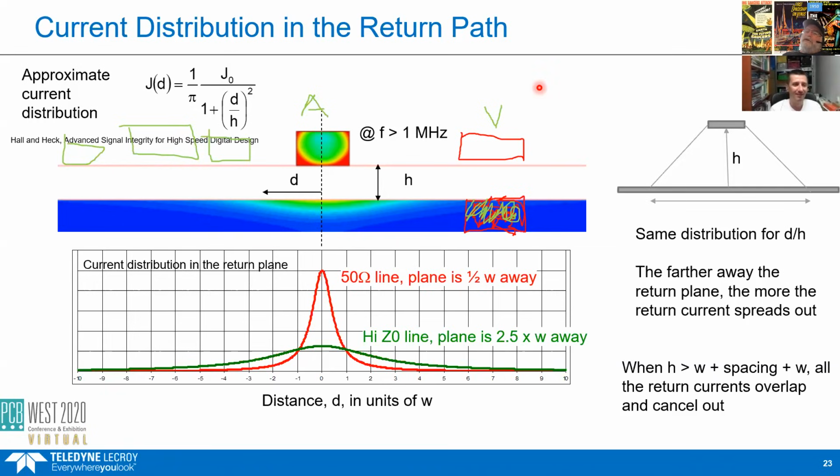Yeah. One other thing you have going for you when you make a small board is, for a given rise time, the shorter you make the interconnect, as long as it's electrically short compared to the rising edge, you will always reduce the crosstalk. And so if you make your interconnect short enough, then, hey, you can keep them really, really close, and the amount of crosstalk you get is reduced.